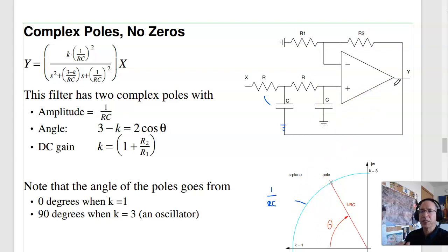Typically, you don't really care. What the DC gain does is it adds gain. Typically in the amplifiers, I'm going to want to amplify my signal anyway. This will give you some of the gain. The circuits we looked at before will give you the rest of the gain, like the inverting amplifier, non-inverting amplifier. So this one just kind of match the denominator and live with the numerator.